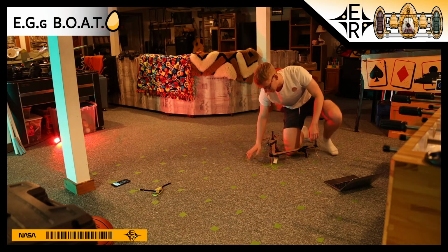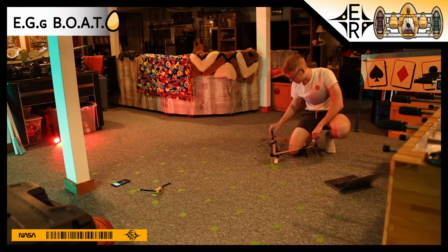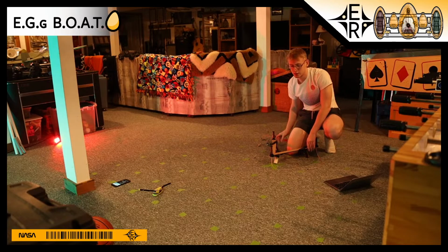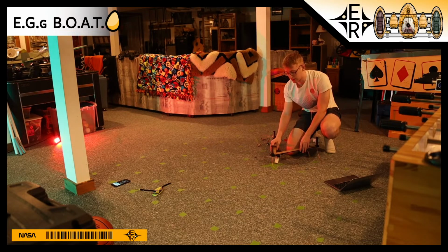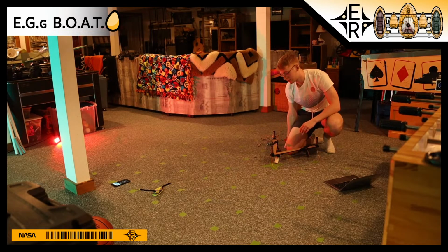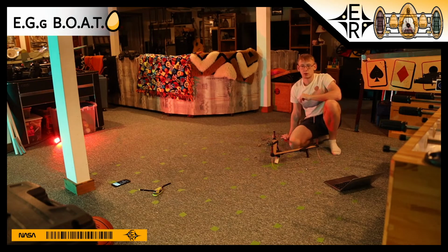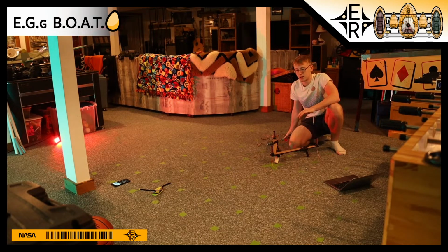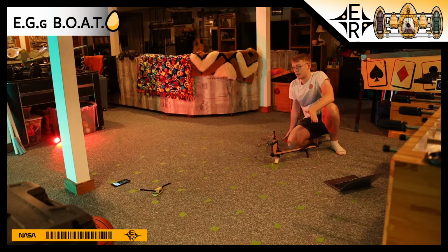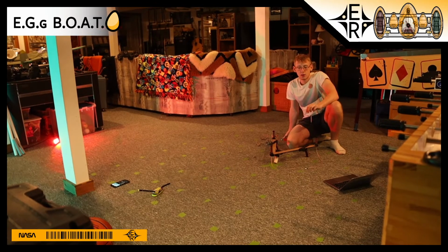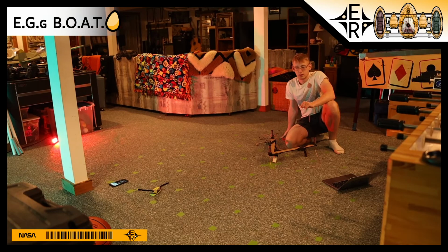Alright, so we've got this grid here. Talked about it at the beginning of the stream, but it's just a 9x9 grid. Each dot's about a foot apart. We'll put the reference antenna at the center, and once we get everything set up so we can start doing some testing, we're gonna place the beacon at each of the different dots on the 9x9 grid, measure the 4 analog outputs of the phase comparison circuit, and then move it to the next grid cell and do it for all of them.